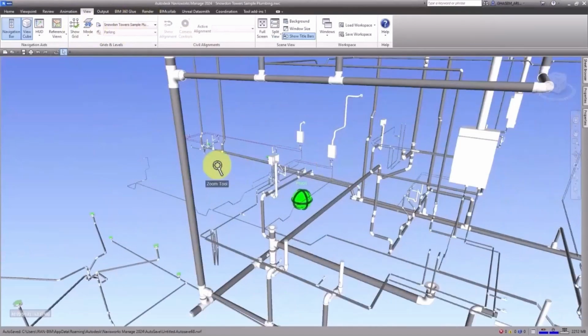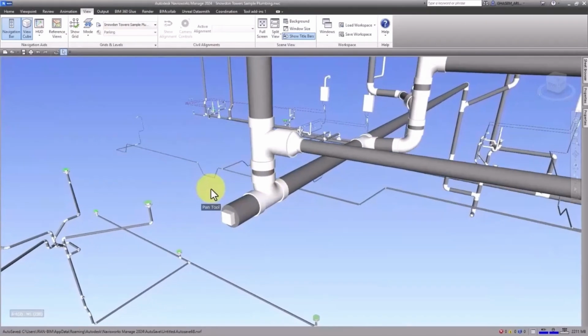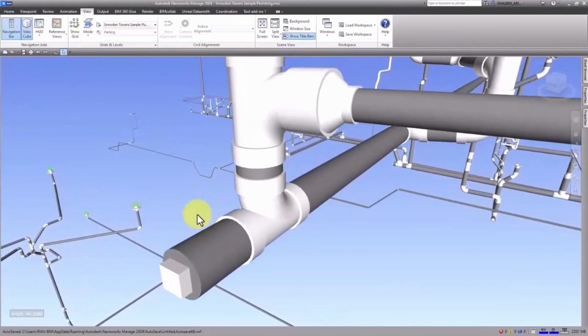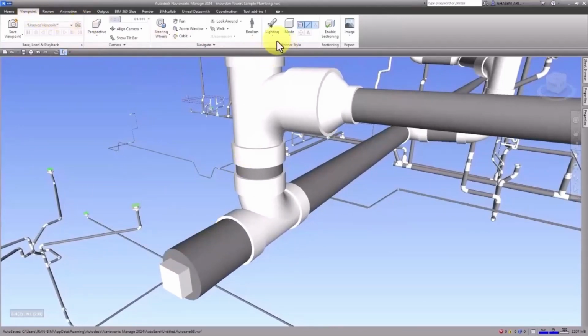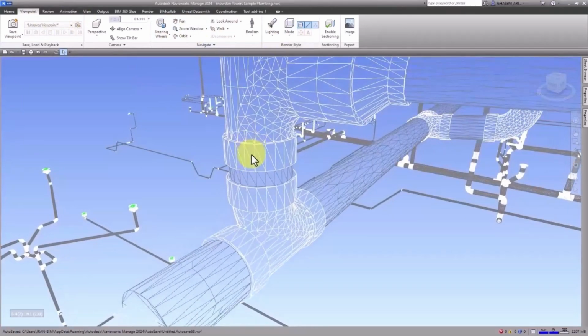Okay, as you can see, here we have some curves. Guys, when you want to check the overlappings in Navisworks, this software converts all of the elements to some shells, and all of those shells and surfaces consist of some triangles, each of them with 3 sides. Guys, we can say that we have a hard interference in Navisworks only when 2 triangles from 2 different elements are facing with each other.